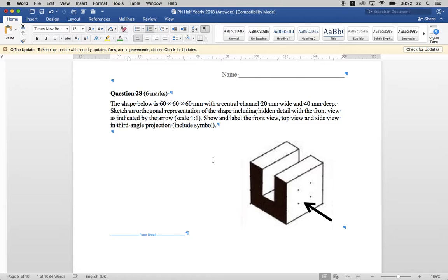So I think that's labeling. I think everyone labeled more or less okay. Some people's label was a little bit off, and maybe their line work was a little bit off, and I took off, say, half a mark each, to make it 1 mark. Your line work should be all capitals. Your lettering should be all capitals, and it should be 5 millimeters tall. That's the standard set out by the Australian standards and reinforced by the Victorian government as well, in the document that I posted for you guys.